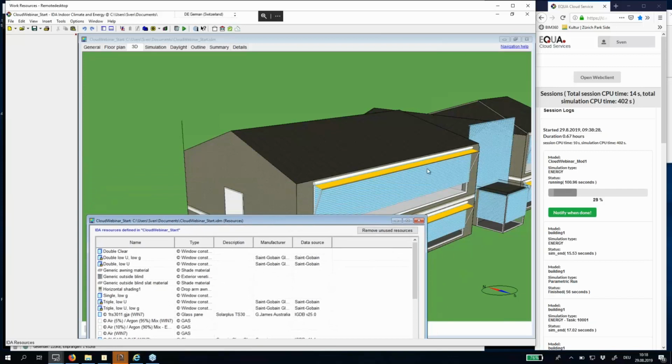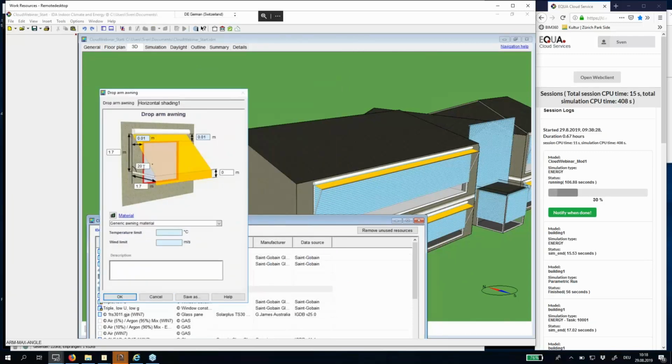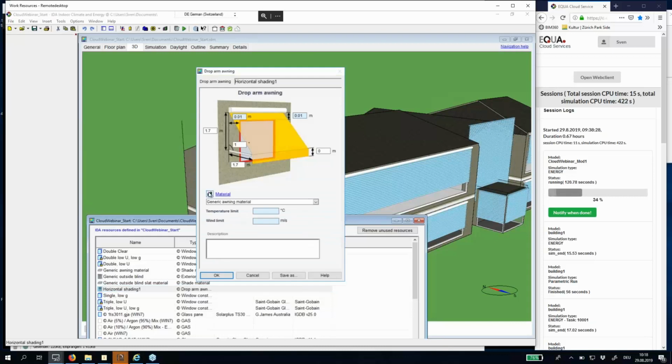All these simple screens refer to 1 single resource called horizontal shading, and if you vary this parameter in this resource, so you can go to 1 degrees for instance, all these horizontal screens will actually disappear, and I can make them large again.